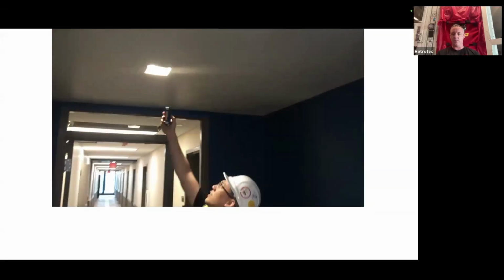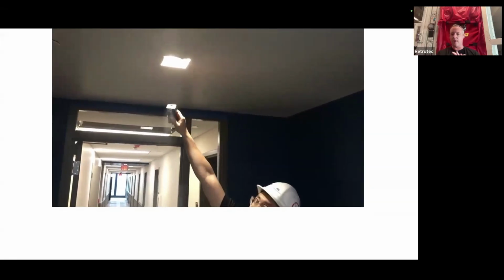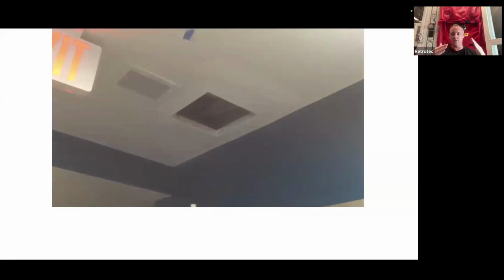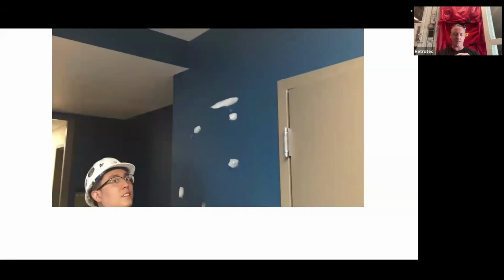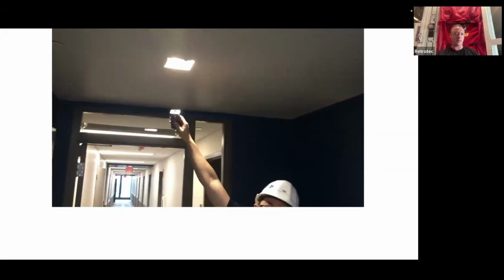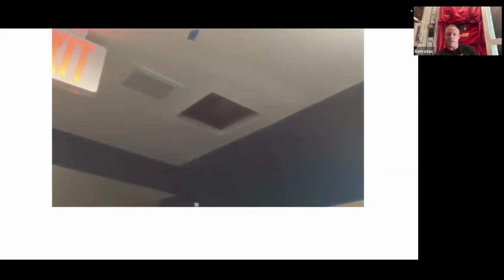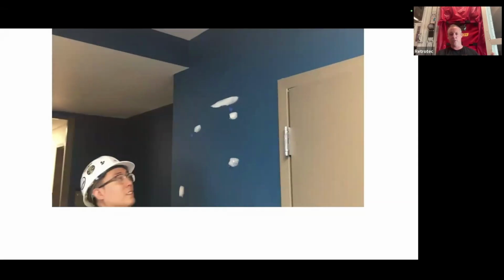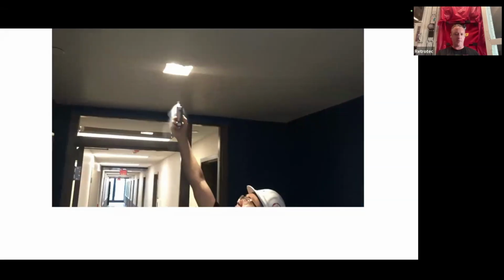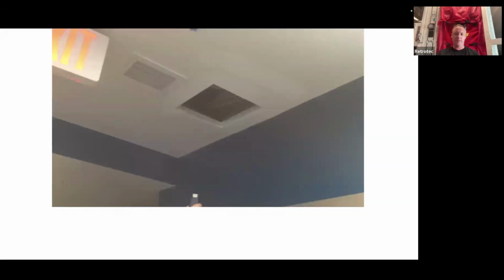In this case, we just reported to the GC what we found, and they know how they put it together. They know where those connections are of those dissimilar materials, so they could easily go in there and find it. That's a quick and easy way to prove that it's there. This was a large dormitory building, so I think we had about 14 fans set up downstairs to give us that pressure. You can run your blower door in either direction. Here we depressurized, but you can also pressurize and watch that fog go into the leak.